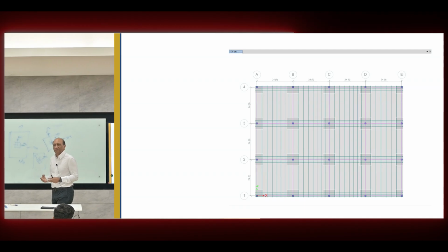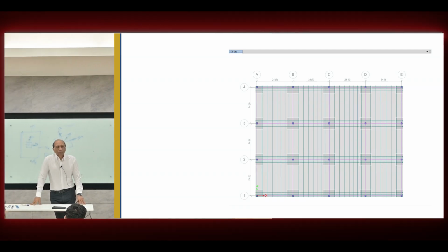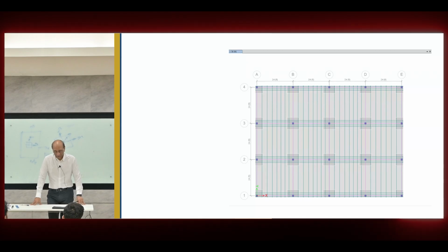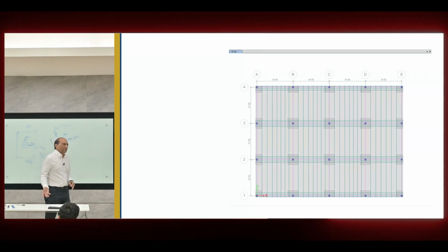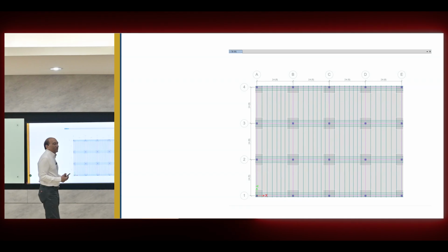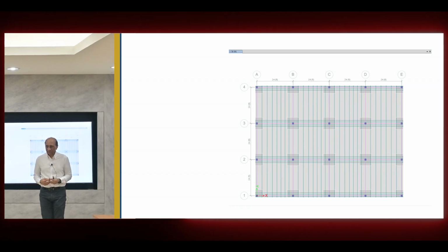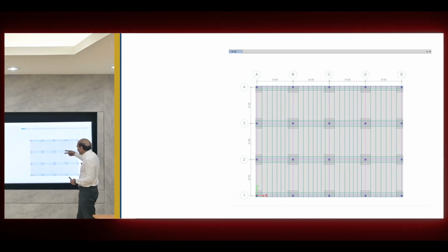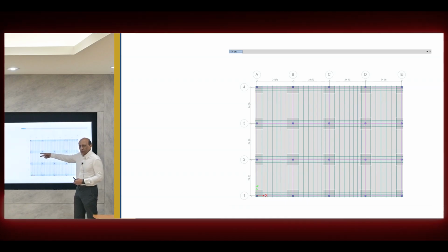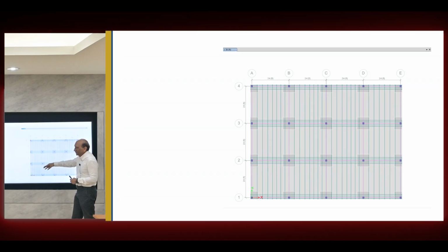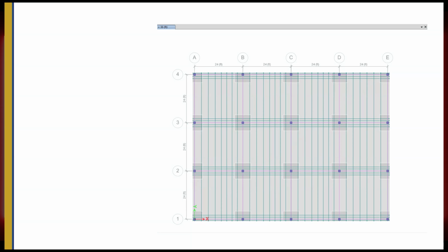Because you cannot have a good, realistic post-tensioning in two directions. It will disturb the system. We want to carry the loads in a very well-mannered structure. So normally, two-way slabs are converted into a kind of one-way system for post-tensioning purposes. In this direction, these bands are closely spaced tendons. They are supposed to be the supports now, like a hidden beam. And in the other direction, we just put them uniformly. This is for simplicity of construction and also for the behavior.